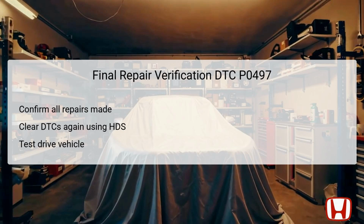Following this, it is essential to perform a test drive under conditions that originally triggered the DTC. Monitor the system closely during this drive to ensure that the issues have been effectively resolved. This step is crucial to ensure no further issues arise, thus confirming the successful repair of the EVAP system.